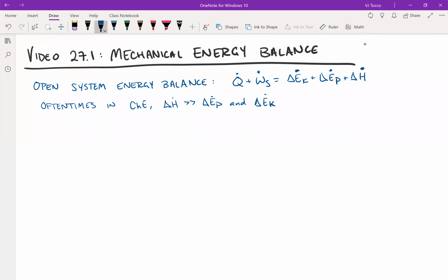In this video, I will discuss the mechanical energy balance. I'll start the discussion by quickly reviewing the open system energy balance. Q plus shaft work is equal to the change in kinetic, potential, and enthalpy. Oftentimes in chemical engineering, we say that the change in enthalpy is much, much greater than a change in potential energy or kinetic energy, and therefore these terms are oftentimes canceled.